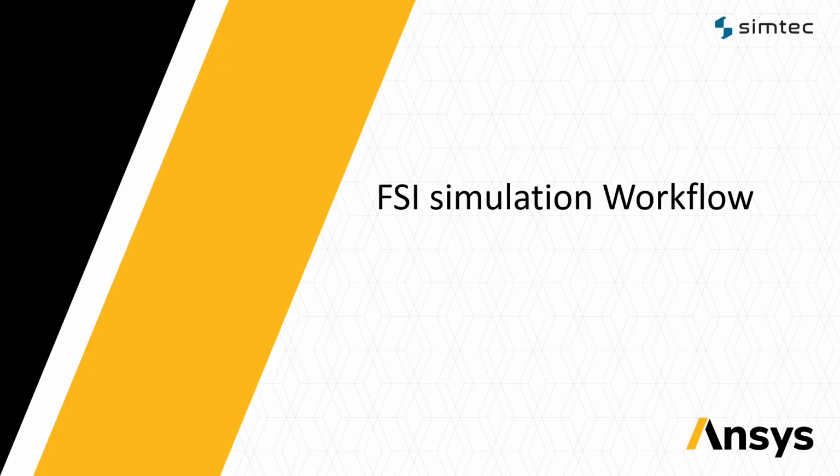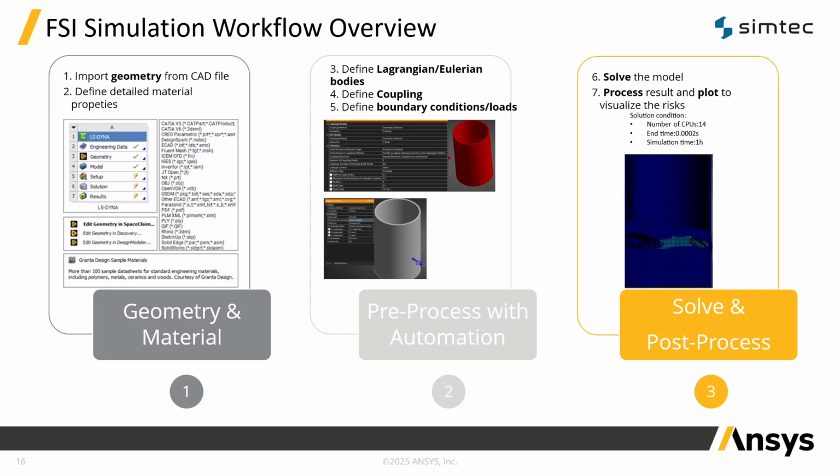Now, we'll be looking at an example workflow for FSI. Let's now go step by step through one example of an FSI workflow in LS-Dyna. As in any simulation, we must import the geometry. After that, we must carefully define the material properties, as this is very important.